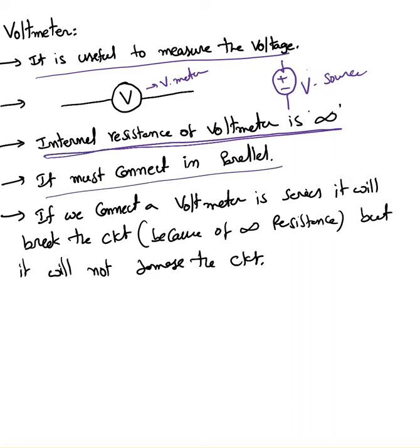If we connect a voltmeter in series, it will break the circuit. I mean, that means it will open the circuit. I think open is a better word. It will open the circuit because of the infinite resistance, but it will not damage the circuit.